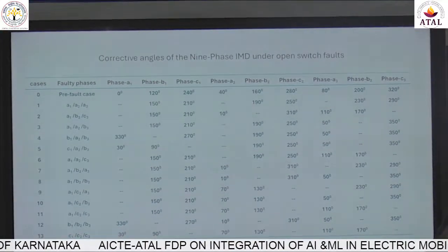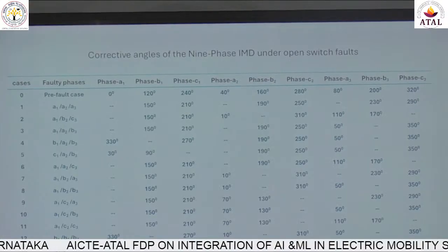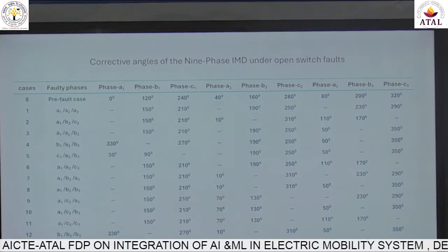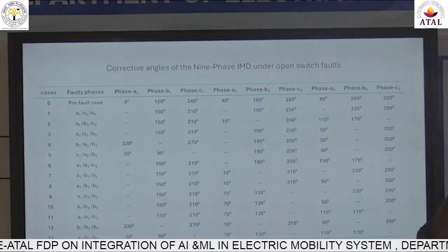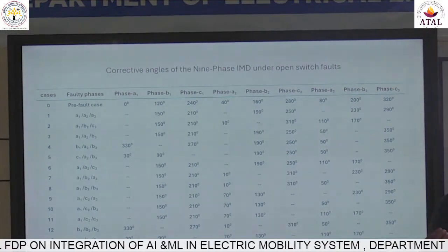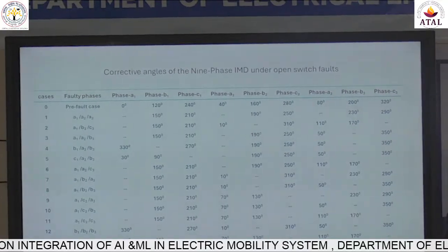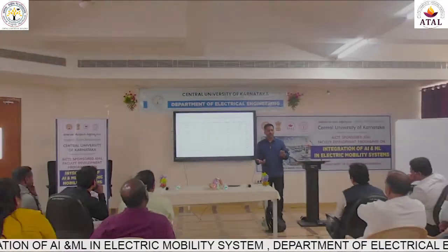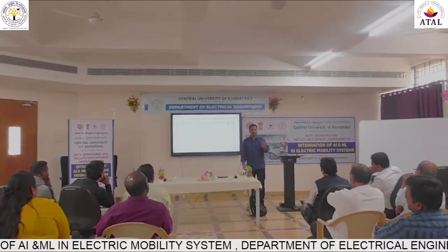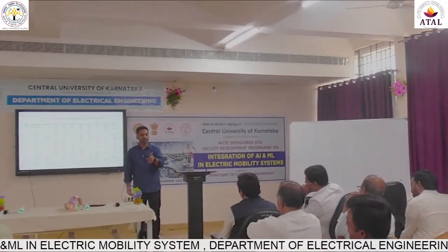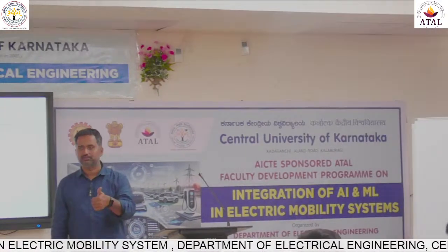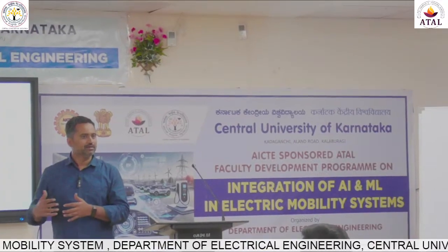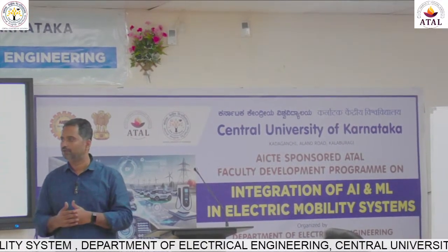The reason, as I told you sometime back, is that the number of slots and the conductors in the slots is the same, whether it is 3-phase or 15-phase. Now as the number of phases increases, what is the volt per phase? Reduced. When it reduces, the DC bus voltage requirement will come down, which is not advantageous. And all our devices are ready to take higher currents rather than higher voltages. Paralleling of devices can also be avoided here because of multi-level windings and all of them.